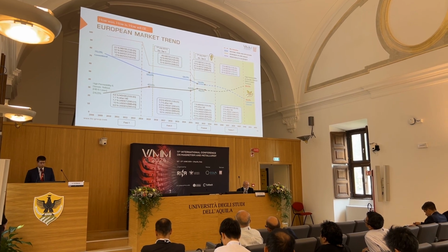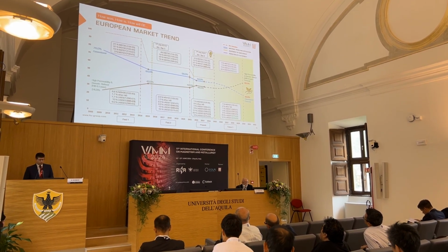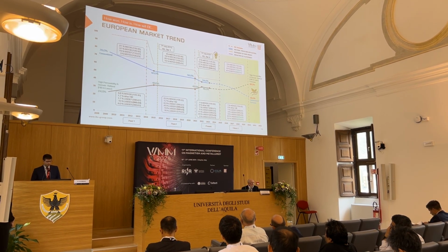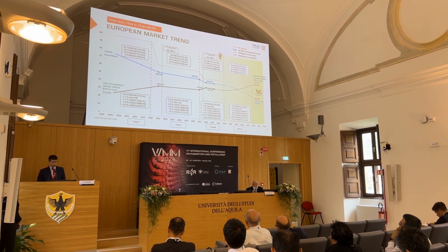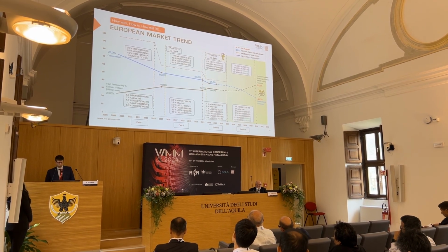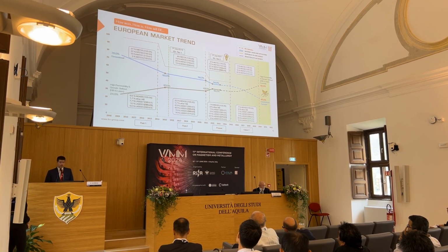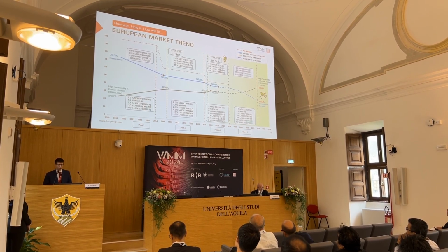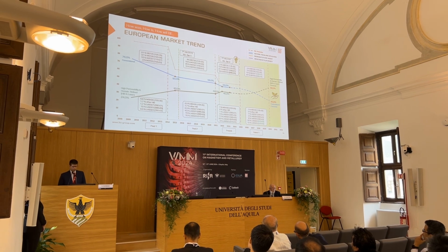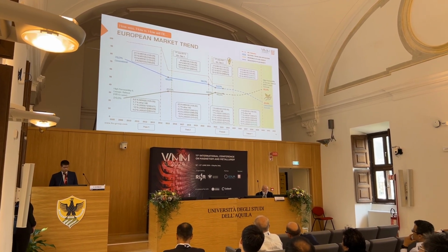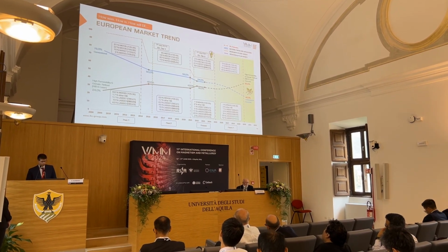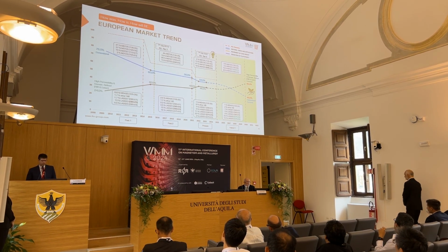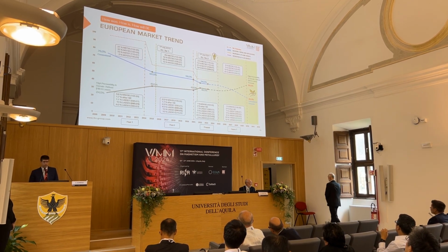Just one step ahead, when we go into the Tier 1, everyone had to make some change in the design, and we can see that in the conventional we already have 15% of reduction from 2008 to 2015. And this reduction is showing that the trend is to make a transformer with lower losses, as requested by the eco-design. And this made the change from material like M6 T35 and M5 T30 to material like M4 T27 and M3 T23.